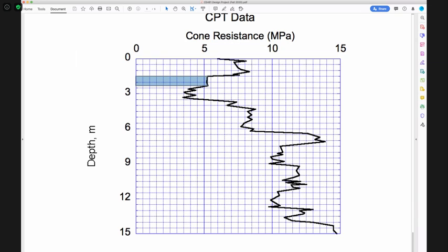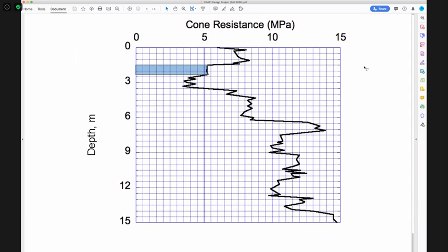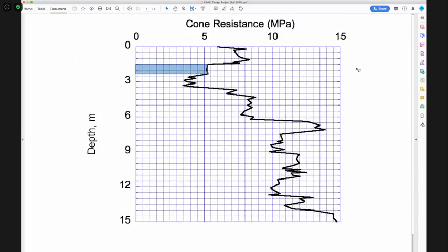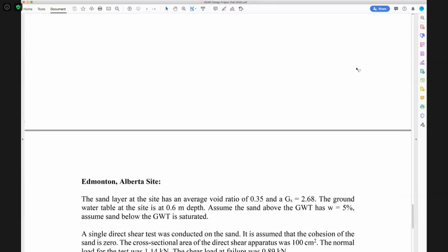And it's not worth getting into 65 layers or anything like that. But I also don't want you coming up with 2 layers, because there's decidedly some variation here that you should be able to capture. And that is, by the way, a huge benefit of the Schmertmann technique, is it is based on CPT test, where it has this ability to refine your assessment of the soil parameters quite nicely with depth. And that's it for the packet that describes the design project.